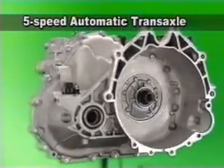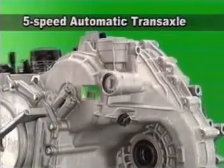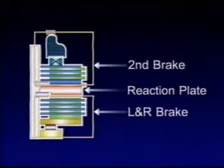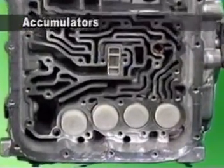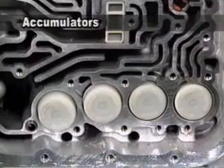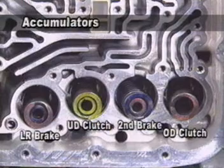For 5-speed automatic transaxle, as explained previously, one-way clutch is additionally installed on the sub-transaxle. Reaction plate is bandless type, which can be used commonly for both second brake and low and reverse brake. The function of accumulators is to absorb pulsation when the solenoid valve is applied, and also prevent sudden pressure drop when the solenoid valve is released. 4 accumulators can be distinguished by their spring colors.